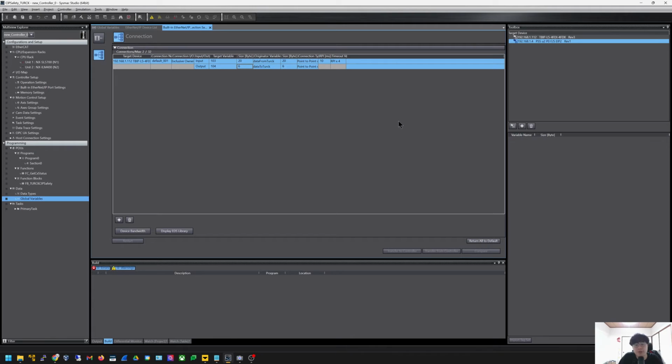That's why the reason that I use bytes, don't use words, because in OMRON also they count all the data in bytes. And choose the metadata, what variables you want to map, and then finally the connection type. You can choose point-to-point or multicast. And then you need to enter your RPI. In my case, it's 10 milliseconds. Done. Then you finish the Ethernet IP connections.